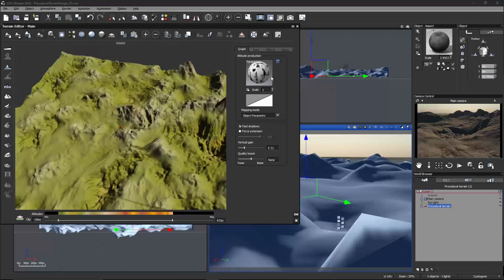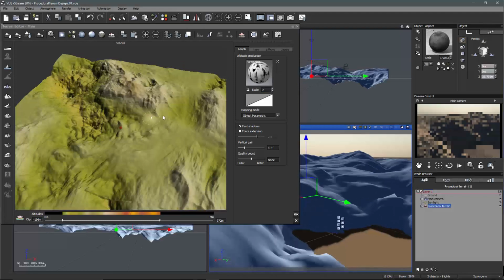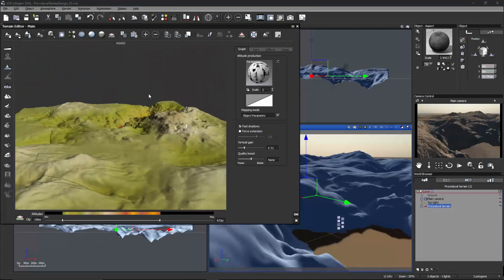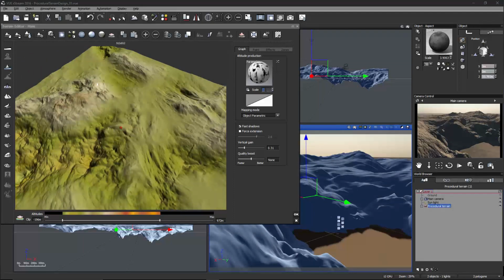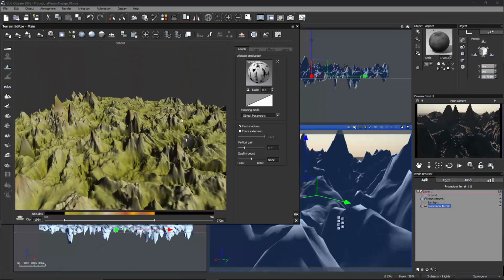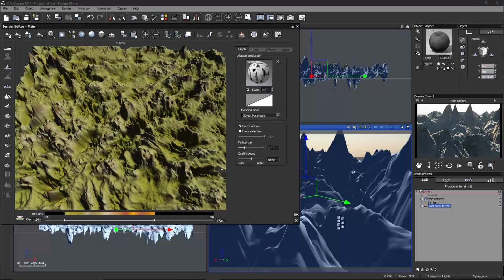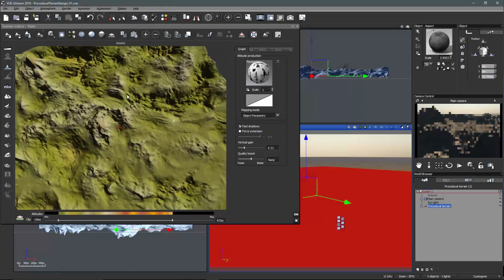What we could also do is just set the scale a little higher if we wanted, or a little lower. Setting it to 2 brings us back to the scale we were at before when we had it set to 1 kilometer. We can go back to 0.5, and that would be like extending the scale to 0.4 kilometers, but the vertical gain is then different. So it changes the height, as we can see here, which is why it's easier just to use the extend terrain canvas, so that way you don't have to worry about matching up all the elevation levels.